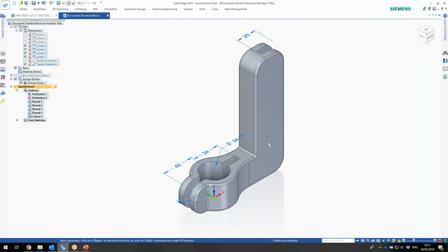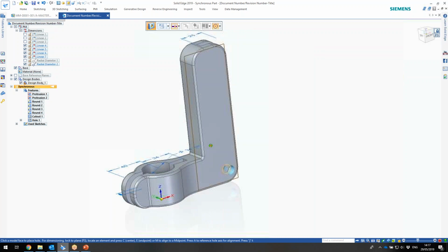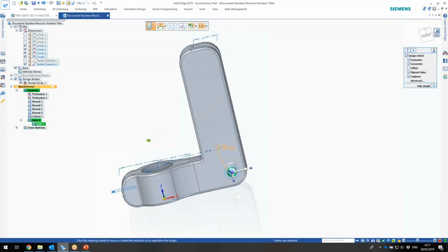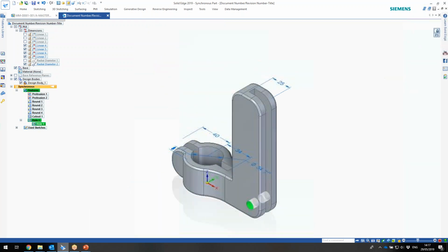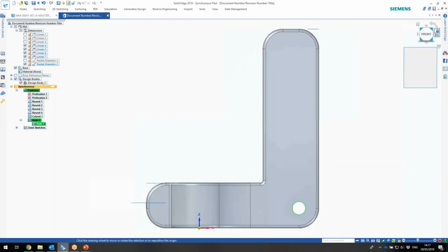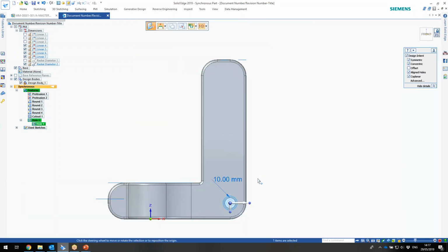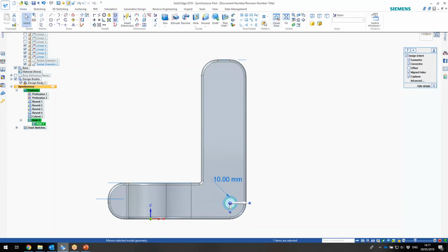It's rounded. We've got the slot through. Now we need to add in some holes for the clamp arm to bolt onto. So add a hole. Again, the useful padlocks come up again. Click 3 on the center there. Sometimes you can get a little bit lost with the cube, but I find it very helpful to use that cube to reorientate me quickly. So now I need to make a pattern of holes up this arm.